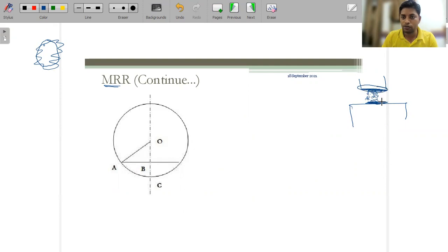Okay, the same cross sectional area will be here. Why I'm saying same cross sectional area is because in this region, there are a number of abrasive particles. These abrasive particles are in contact with the tool, and when the tool is vibrating, these abrasive particles will start vibrating. Whatever abrasive particle is below that will also start vibrating, and similarly it continues.